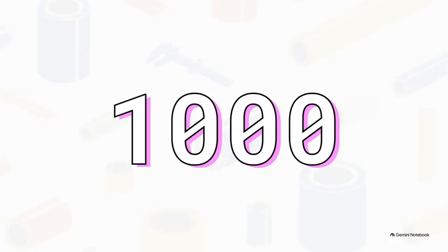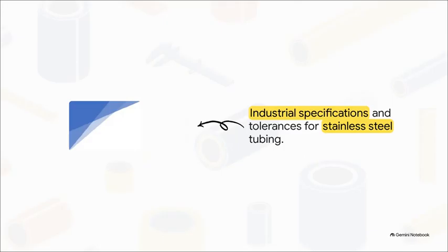In this neat little equation, P stands for the internal design pressure of the system, and S is the allowable stress of the specific material you're using. So this formula is basically the mathematical proof that higher schedule numbers will always mean thicker pipe walls to handle greater pressures. Makes perfect sense, right? But hey, defining the thickness on paper is really only half the battle. Actually manufacturing it consistently, that's the other half.